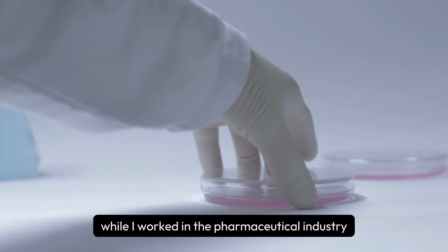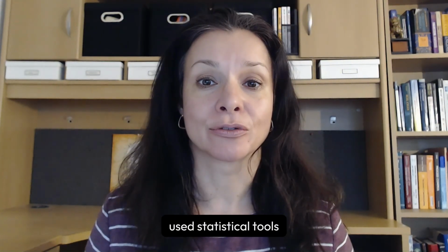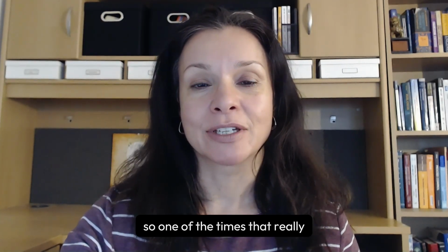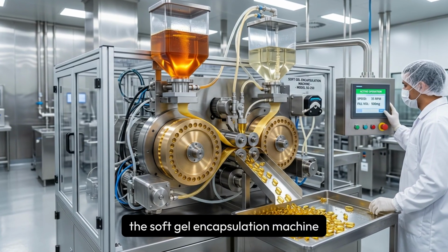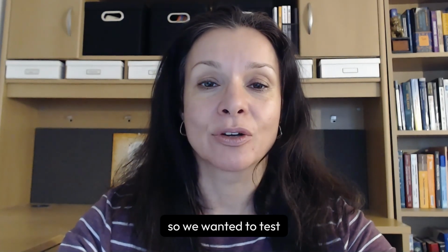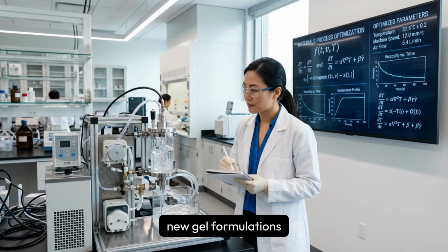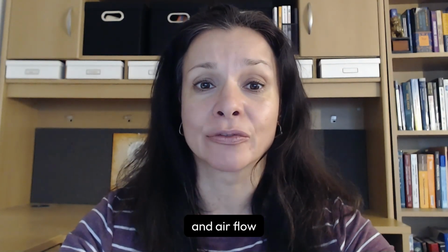When I worked in the pharmaceutical industry and the semiconductor industry, DOE became one of the tools that I reached for constantly, and it was one of the most heavily used statistical tools that I used during those years in industry. One of the times that really proved valuable was when I was starting to work on the softgel encapsulation machine, and I was tasked with creating a mathematical model of how that machine worked to help automate it. We also wanted to test, in research and development, new gel formulations and optimize the machine parameters, such as temperature, machine speed, and airflow.